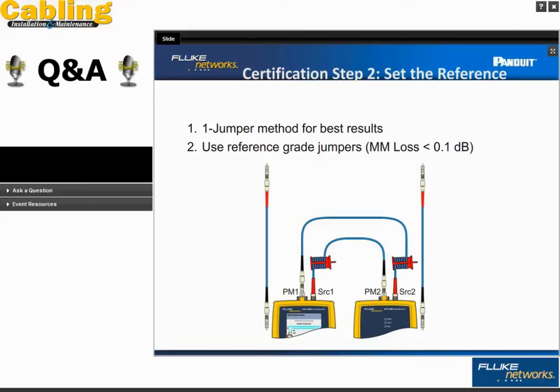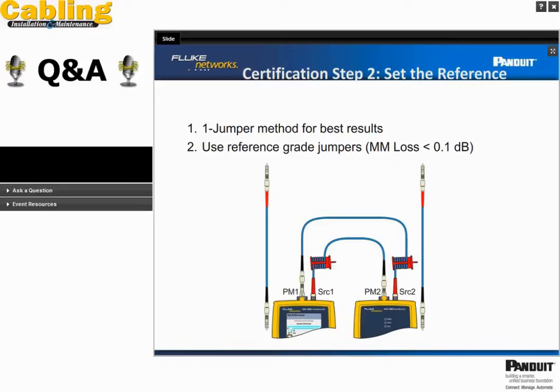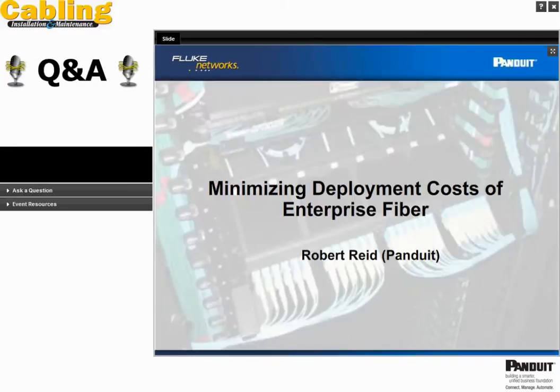It'll strip away the higher order modes as was designed in the standards, with that diameter mandrel, because obviously there's a different diameter mandrel for each of 62.5 micron and 50 micron. There is some work underway to figure out what diameter of mandrel you would need for bend-insensitive multi-mode fiber in order to accomplish the same thing, but that's so far, to my knowledge, incomplete.